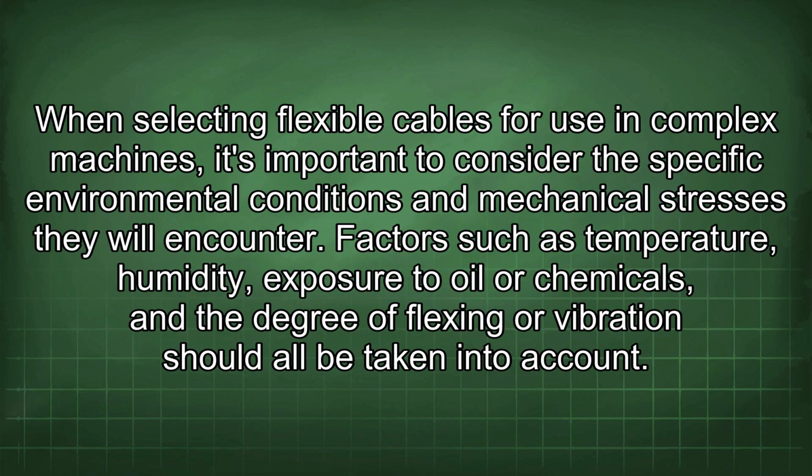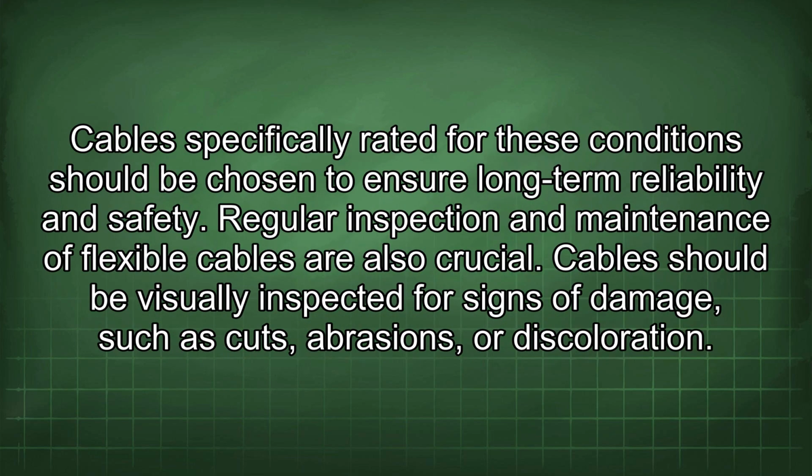When selecting flexible cables for use in complex machines, it's important to consider the specific environmental conditions and mechanical stresses they will encounter. Factors such as temperature, humidity, exposure to oil or chemicals, and the degree of flexing or vibration should all be taken into account. Cables specifically rated for these conditions should be chosen to ensure long-term reliability and safety.